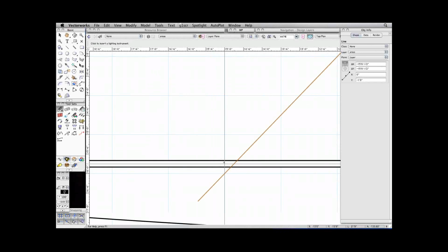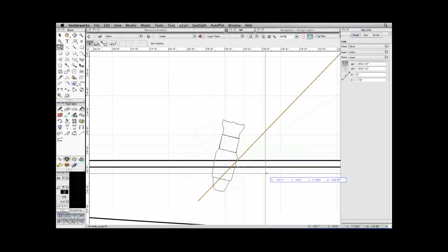Instrument insertion tool, I'm going to position this. One of the things that I didn't touch on today was setting up grids and so forth. But you might notice there's an 18-inch grid set up horizontally, so that I know where my closest 18-inch spacing is. So I'm going to go to the closest spacing, make sure I'm sitting on top of my first front of house, and start to place the instrument.